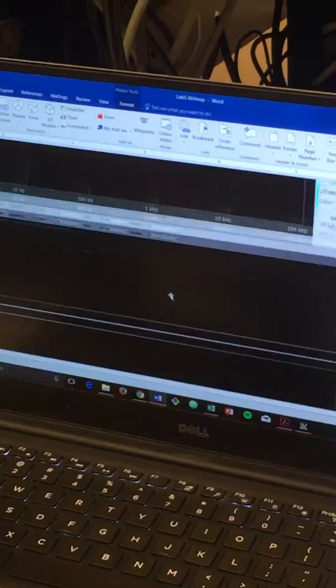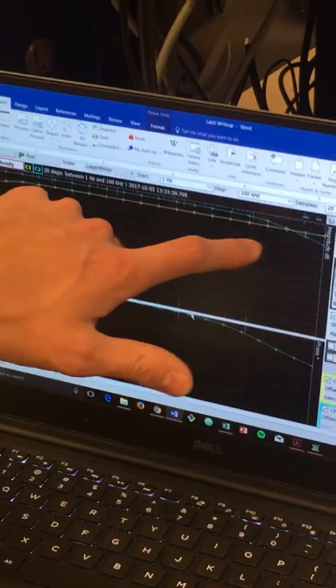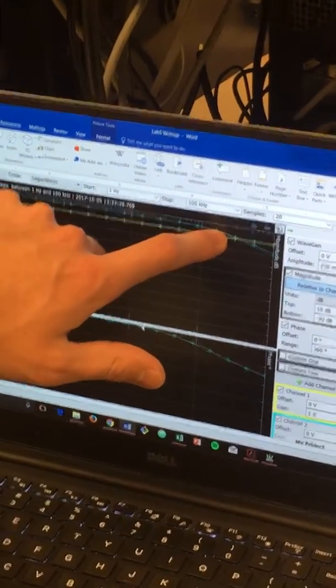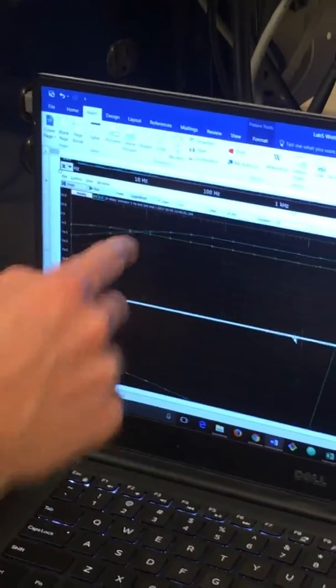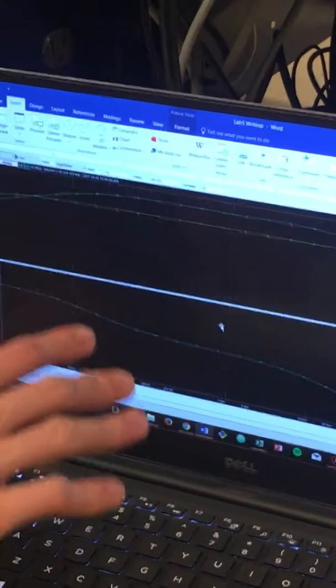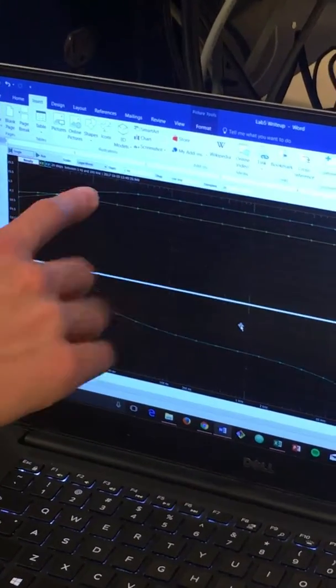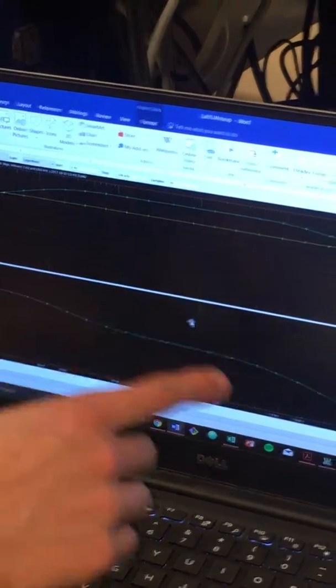And then we also see the 3 dB frequencies are basically just being put together here. So for the low pass filter, the 3 dB frequency is about here, which is about 20 kilohertz. And then for the high pass filter, it's at about 20 hertz. And then here we see for the cascaded, again, the minus 3 dB frequency on the left side of the maximum is at about 20 hertz, and on the right side of the maximum it's about 20 kHz.